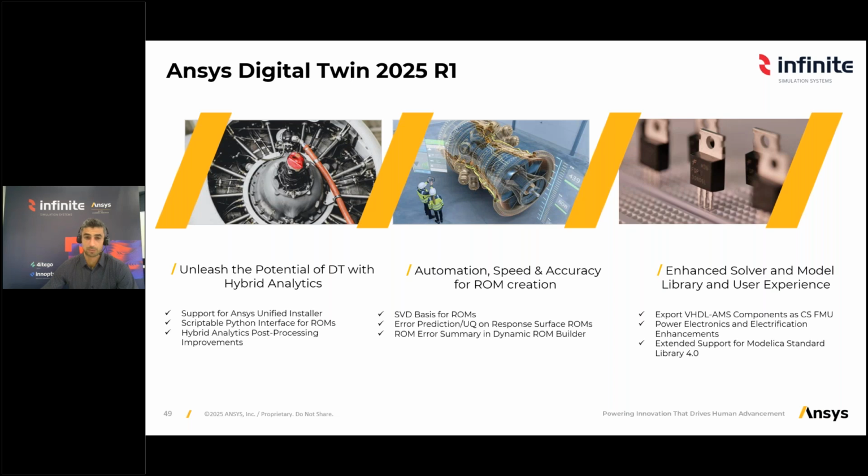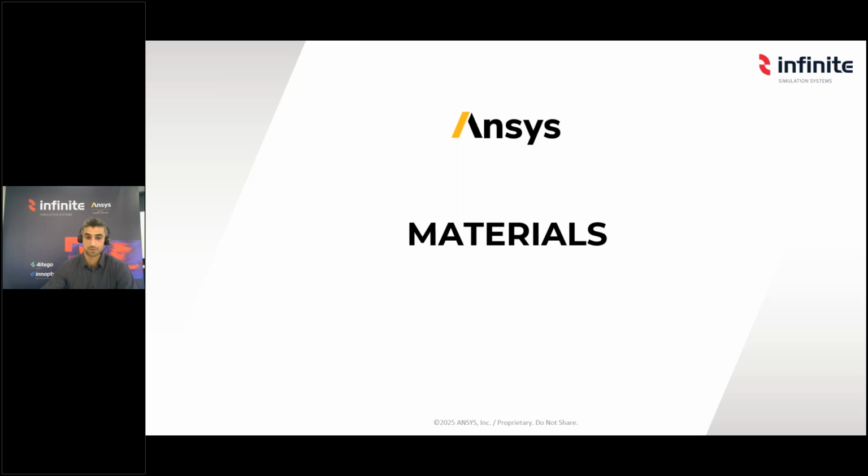there are some improvements on the scriptable Python interface for ROMs, for reduced order models, and also on the libraries which are used for system level analysis, some extended Modelica libraries. So not only on the purely digital twin part with the data coming from the field, but also just setting up your system level analysis, system level model with reduced order modeling and with the use of 0D, 1D components coming off of libraries such as the Modelica libraries.